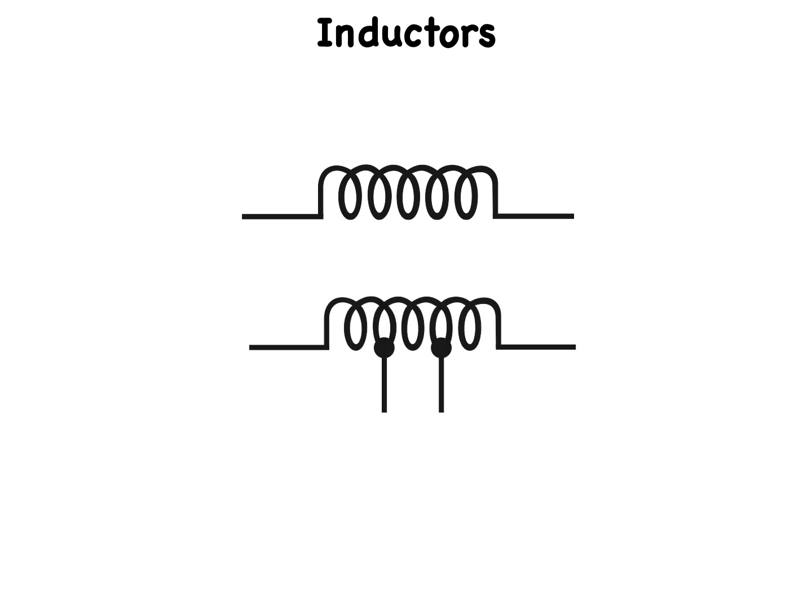This shows the schematic symbol for a tapped air core inductor. In this case, the coil has two tap points along its length. Whereas the fixed coil had only two leads, a tapped coil has three or more. When a coil is tapped, separate conductors are attached to one or more of the turns for intermediate connection. Maximum inductance is obtained from connecting the end leads to the external circuitry.